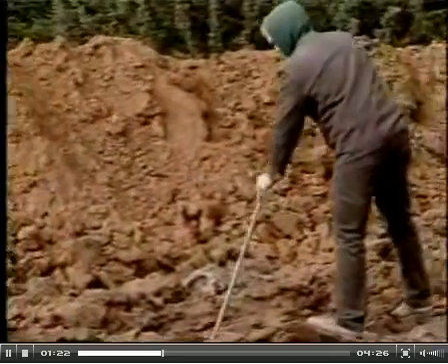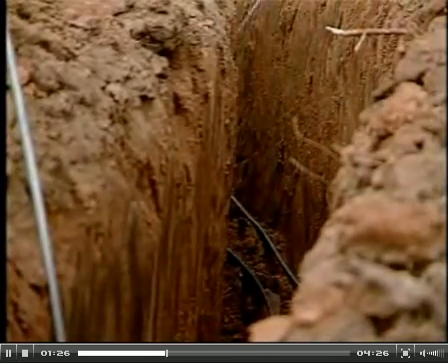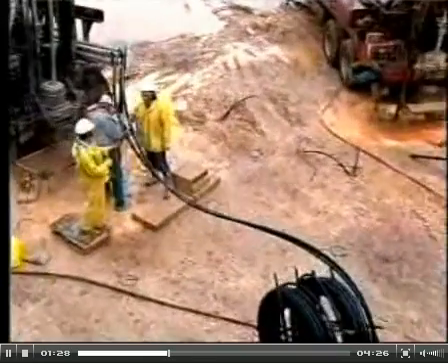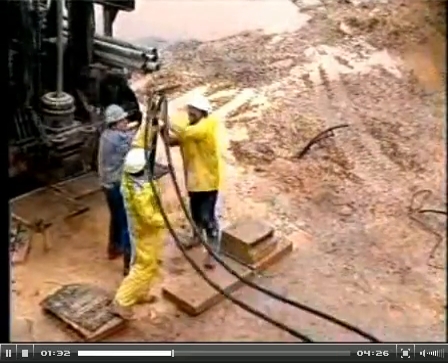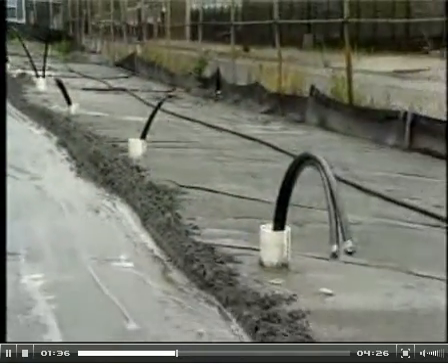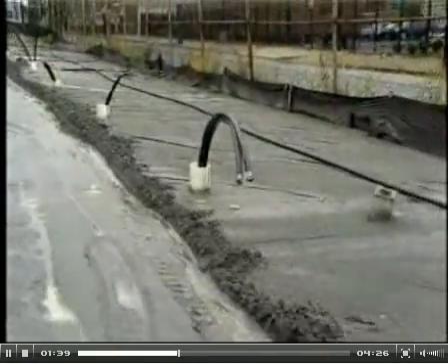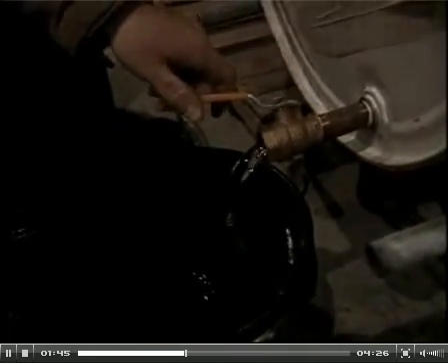The two types of heat exchangers commonly used are open loop and closed loop. A closed loop system uses a system of continuous underground pipe loops in which both ends of the pipe system are connected to the heat pump, thereby forming a sealed closed loop. Water, or a mixture of water and environmentally friendly antifreeze, circulates through the loop to transfer heat between the heat pump and the earth.